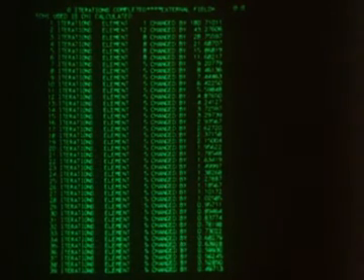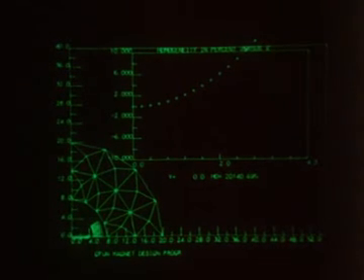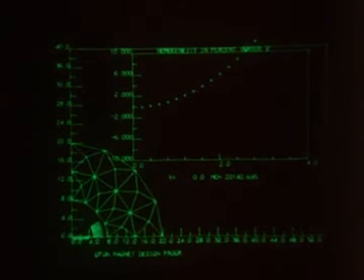The designer now examines the field in the aperture by requesting the homogeneity to be graphed along the mid-plane. As can be seen, the field is only uniform to 10%, and since the requirement is 0.02%, the design must be improved.